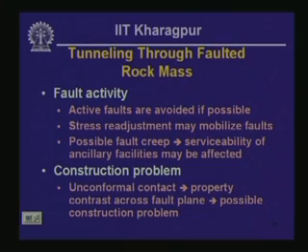This fault movement can generate earthquakes, and those earthquakes are so near to the mine's operation that they are quite hazardous from the point of view of the safety of the tunnels. So, mine-induced seismicity is a big problem of tunnel stability in the case of deep underground mines operating in hard rock areas.